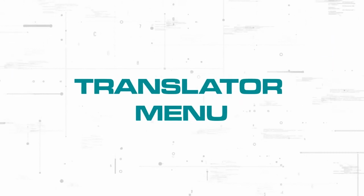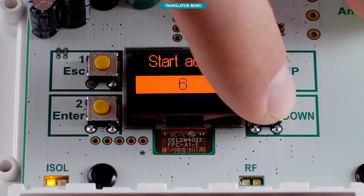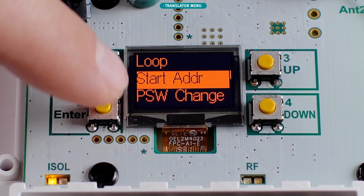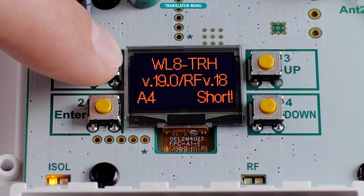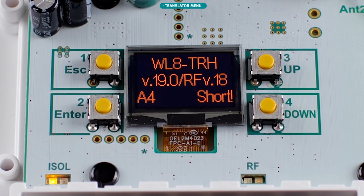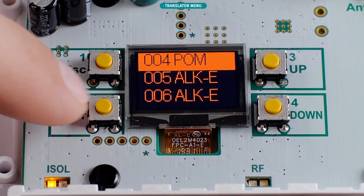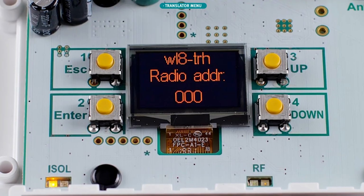While setting up the system, you'll need to specify the starting address in the configuration section of the menu. It will correspond to the translator module itself, and all wireless devices will occupy the necessary number of subsequent addresses in ascending order. In the Loop menu, you can see the full list of occupied addresses and how they correspond to wireless devices in the system.